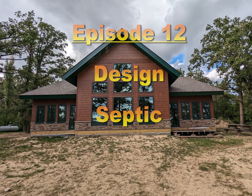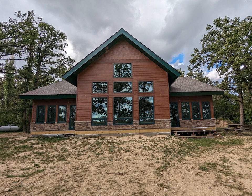Episode 12, Design, Septic. There are very specific code requirements for number of bathrooms, types of tubs, presence of a food disposal. Our existing system was good, but required a larger septic tank. We simply added another tank to the system. We had a 1,000-gallon tank with a total requirement, though, of 2,250 gallons. We needed a second tank of 1,250 more gallons.